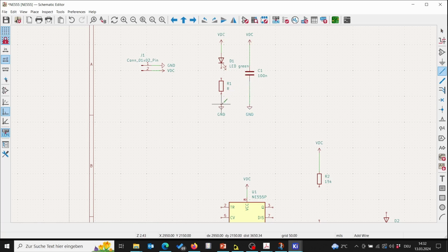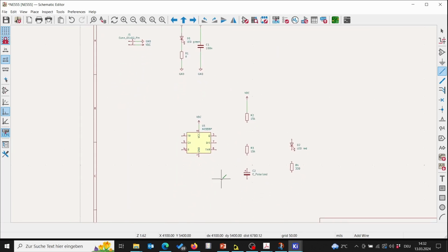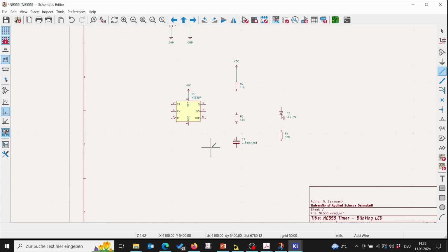Remember, if you just hover over it and you press W, you automatically start the wiring, right? So as you can see, I didn't hit the point, so we didn't connect. We hover over the connecting pin, W, it's connected, and ending here with a left click once. So there are ground pins here.